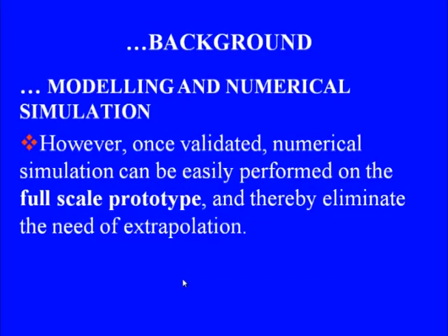But there is one plus point here: once we have validated our numerical model using the results from the physical experiments, which would usually have been performed on a scaled model, we are no more bound by the constraints of the geometry in computer simulation. There are limitations on a physical experiment; we cannot perform physical experiments on the full size prototype of an aircraft or car or train. So because of these constraints, we perform experiments on a scaled model and use the results from the scaled model to validate our numerical simulation process.